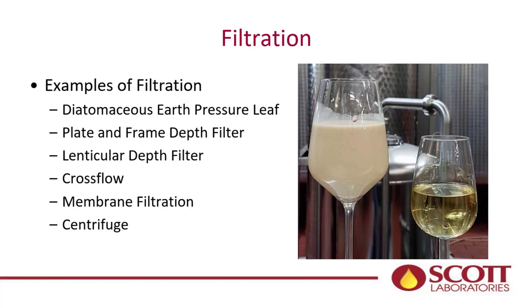These are not interchangeable necessarily. There is some crossover, but there are some eccentricities between each one of these things. And this is not a filtration topic or discussion per se, but I'll get into a little bit of this. You have diatomaceous earth pressure leaf filters, where you add diatomaceous earth into the wine and you build a filter matrix of DE onto a stainless steel screen and pass the wine through it, and the solids are left behind.